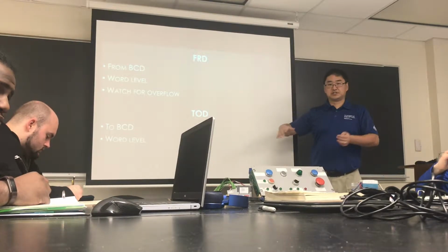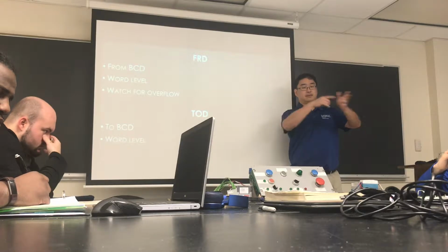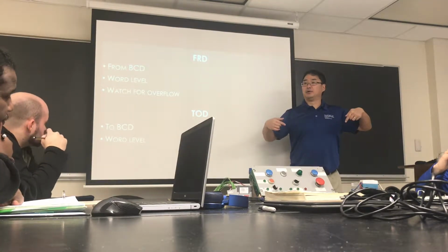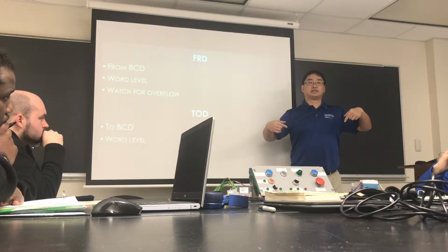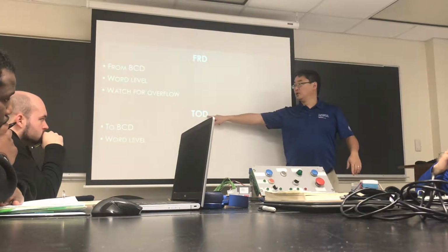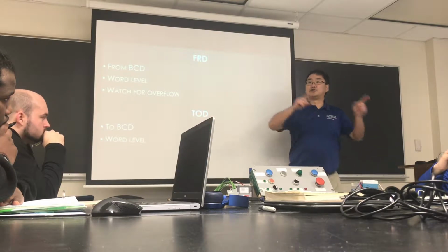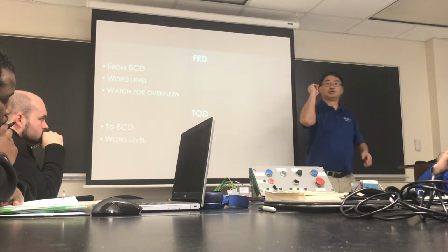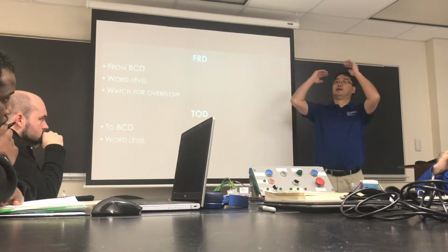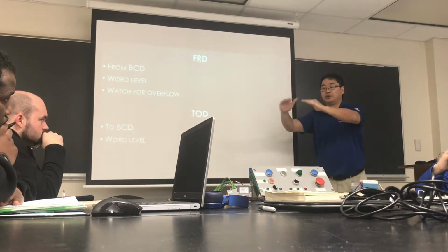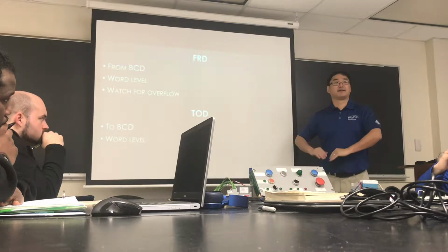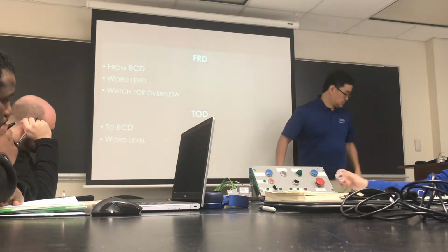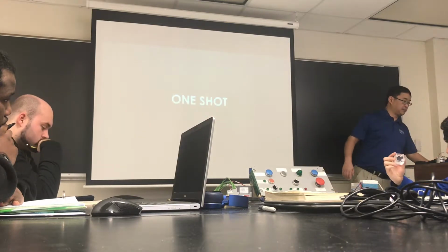I can save the bit pattern for the outputs, convert it to decimal, store it as a decimal, and when I say go, I do a 2 BCD and write it to the output table. And so I can set all the outputs in one quick instruction instead of OTE, OTE, OTE, OTE, OTE. Say that fast more than once, right? I'll show you those in a minute.